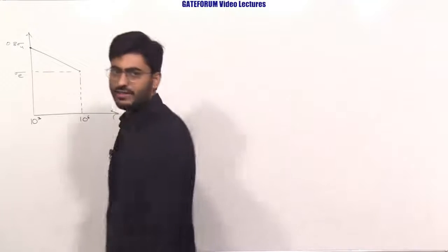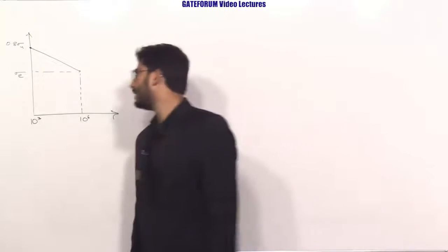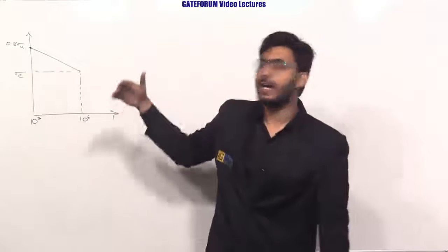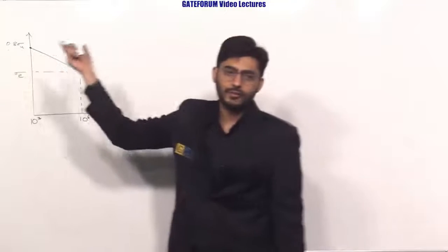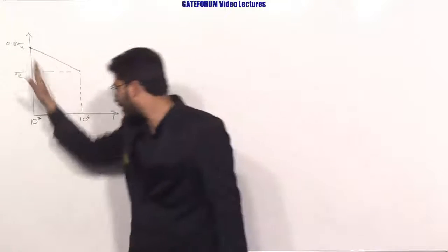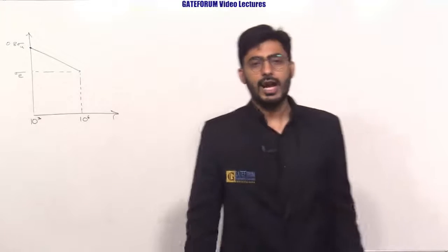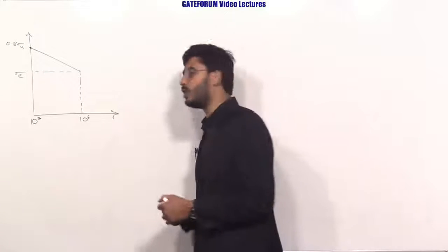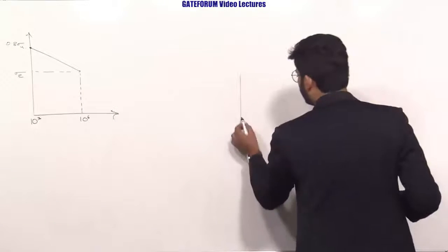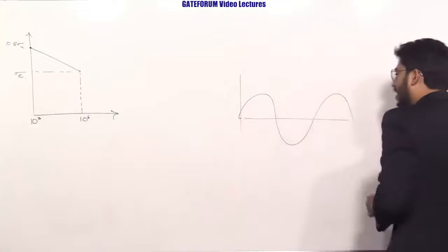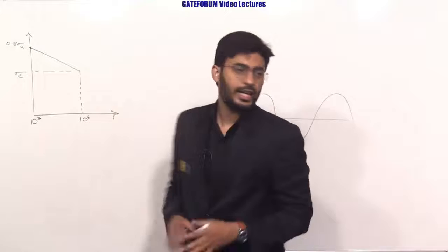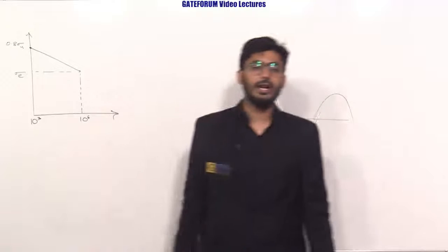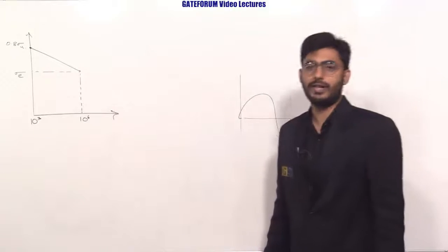Okay, so here he has given the plot to you. In the plot he is depicting that when you are stressing the element at 0.8 times of the ultimate strength, it is able to sustain a life of 10 power 3 cycles. Similarly, in the case of a reversed loading pattern, if you are stressing the element to 250, if this height is 250, then the life of the material is 10 power 6 cycles.